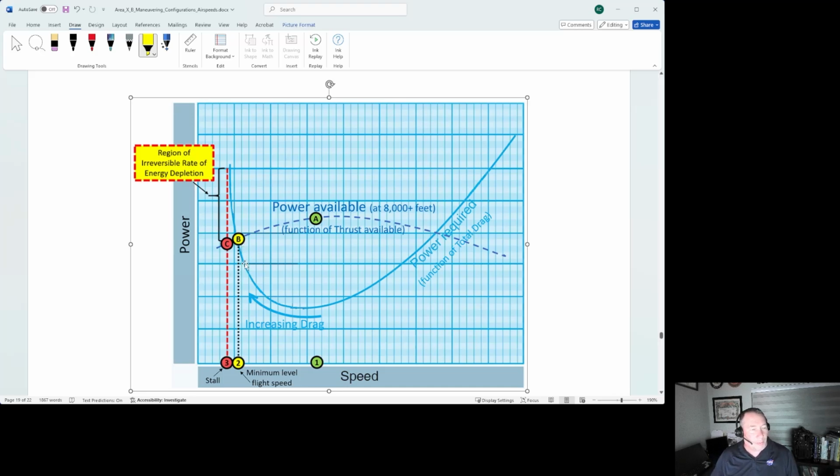Let's say this line represents 50 knots, and on the front side of the power curve, that same power setting will net us perhaps 100 knots. Down here, this could be 58 knots, and this could be 68, 70 knots. Two different speeds, same power setting, on opposite sides of the power curve. I think that's a really powerful takeaway.